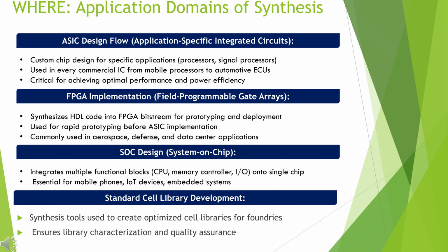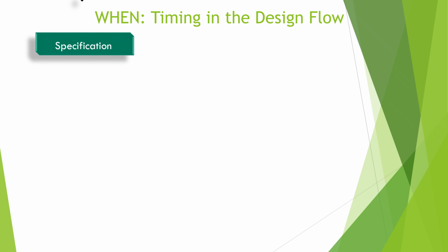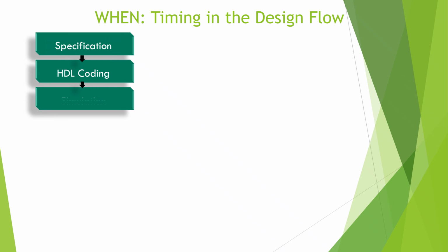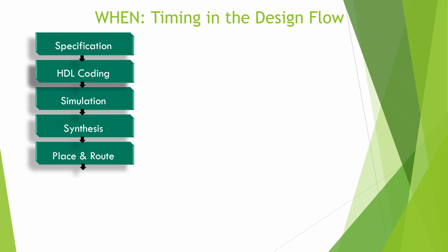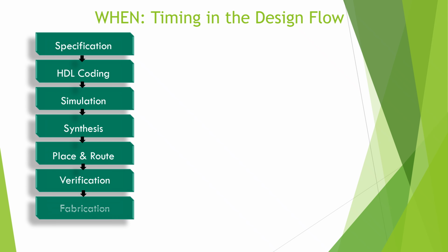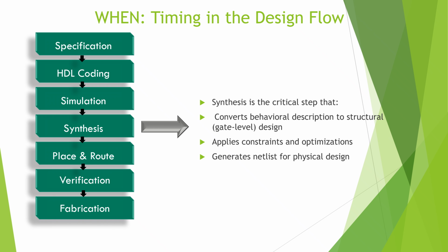So understanding synthesis gives me a foundation to work in multiple domains, ASIC, FPGA, and SoC, not just one. Yes, it is a very transferable skill. Let us place synthesis in the full design flow. The typical order is specification, RTL coding, simulation and functional verification, then synthesis, then place and route, then final verification and fabrication. So synthesis sits after I'm reasonably confident about functionality at RTL level.